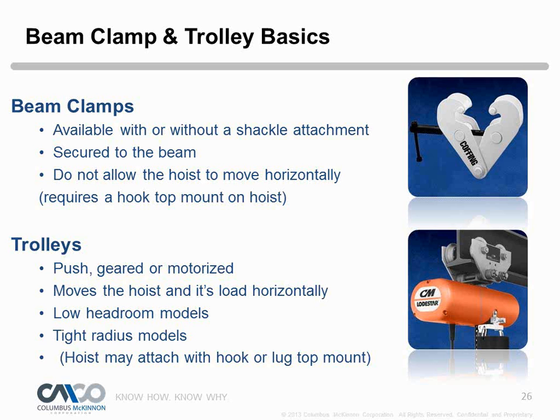Or do we need a trolley? We have push, geared, motorized. If we're going to be traveling a long length, we probably want to go with a motorized trolley. If it's something on a jib and it's a heavier type load, maybe we want to go with a geared trolley where we can just traverse the load with gears, but we're not going a very far distance. And then we have push type trolleys, where it's manual and you pull on the load with ropes or pull on the chain to get the trolley to start moving. So we just get slight movements for push or manual type trolleys.